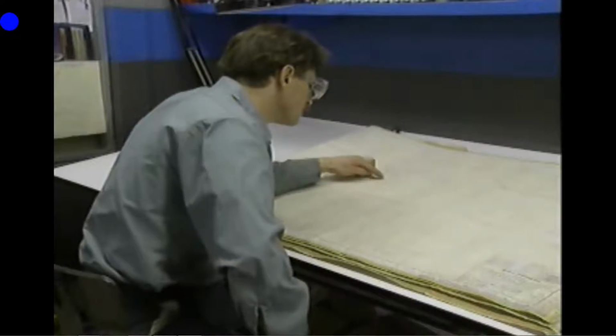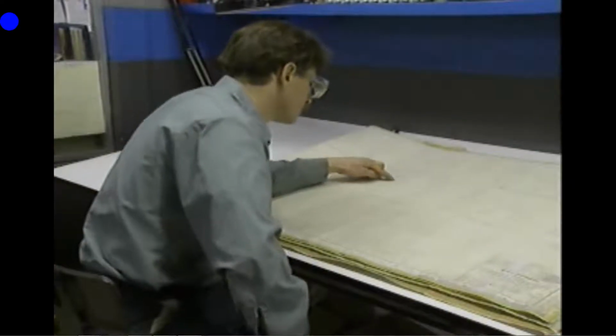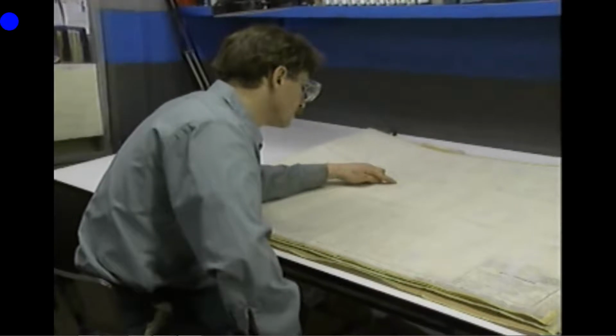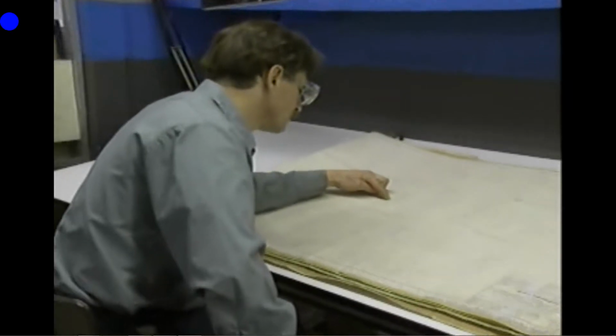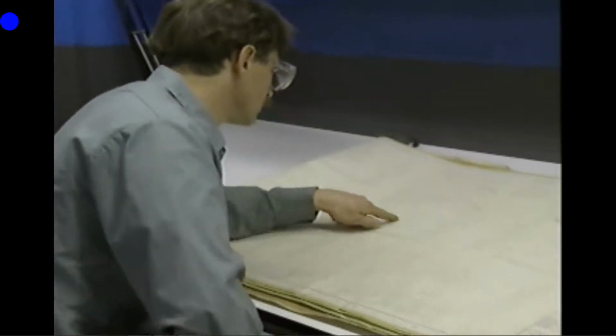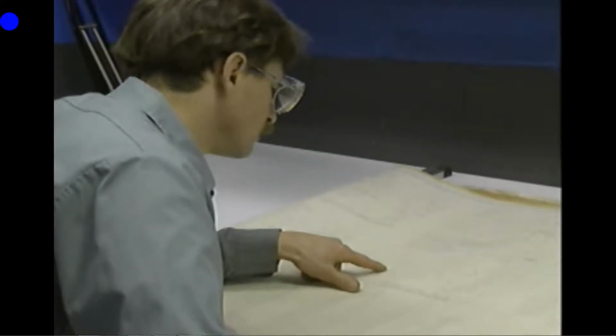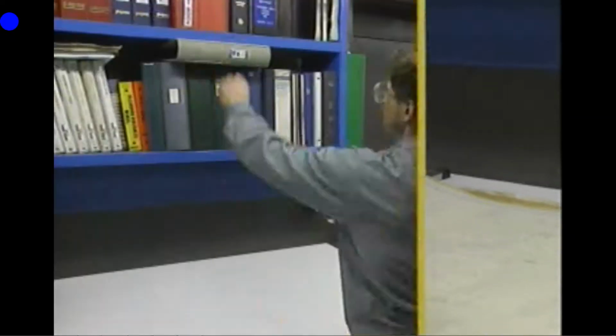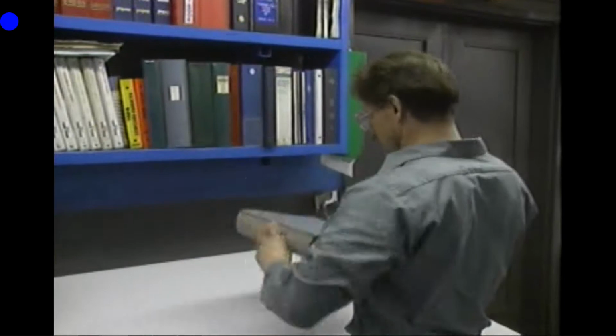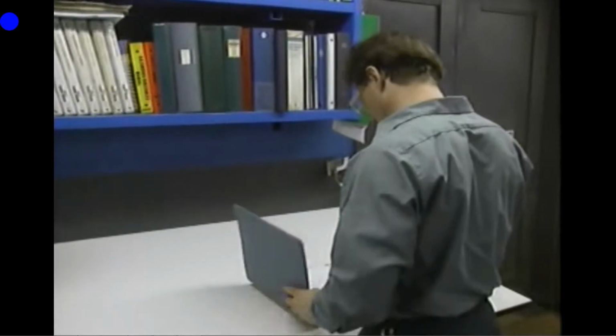Schematic diagrams can help you identify the controller's components and how they are electrically connected. Using a schematic diagram to trace the current paths through the controller is one way to determine how the controller is supposed to work. Other sources of information include system description manuals and technical manuals.